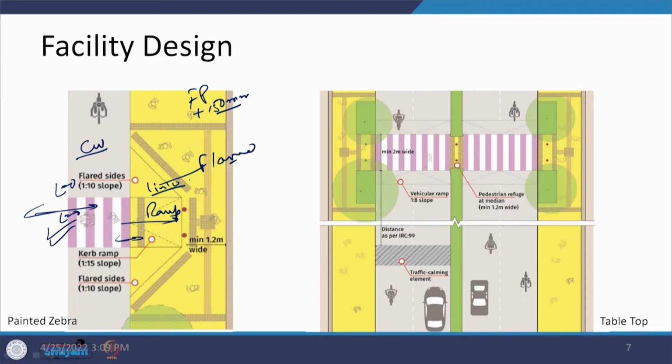Along with these things, what you can see is that the tactile tiles or the warning tiles are also being provided. So, we have the things here which define that you are approaching something beyond this and should be careful about it. And then it allows the person who has nothing to do with the crossing to cross along. So, that is another category of tiles. So, there is a sort of direction tiles which are taking the person straight. But at the location where the crossing is there, again the warning has been issued to the person who is differently abled, that at this location there is something, some junction is there.